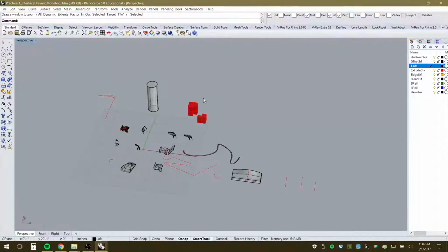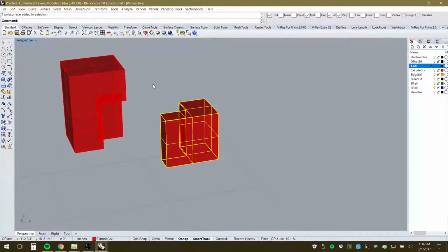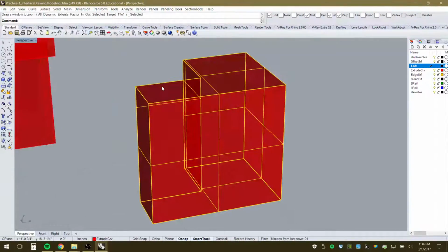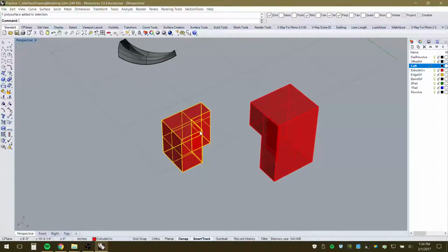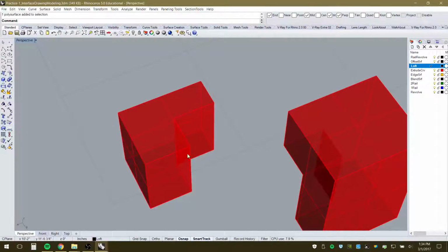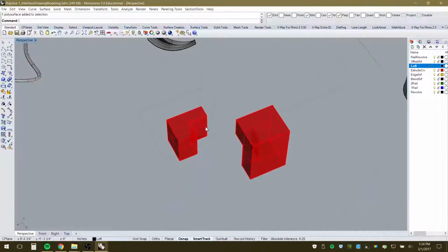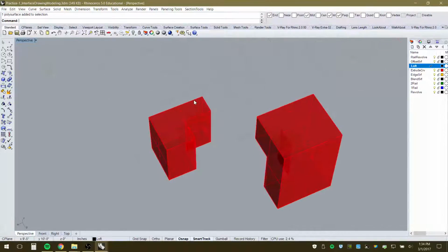One thing relative to what we'll be getting into that you're able to do in Rhino, which gets into fabrication and why we might use digital tools in the first place, is a command called unroll developable surface. Say I wanted to make this box using the laser cutter. I would need the template for all these sides and then have to figure out how to glue it together one way or another. Just like you might find a box that you have collapsed, right? It has flaps and certain areas are folded. You can basically do that with Rhino.